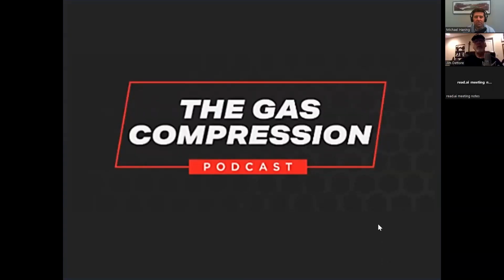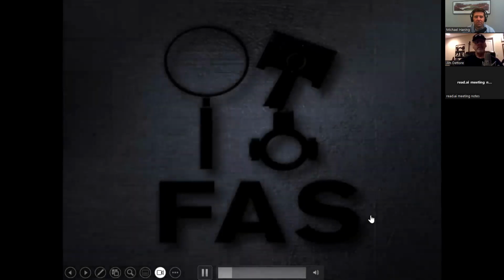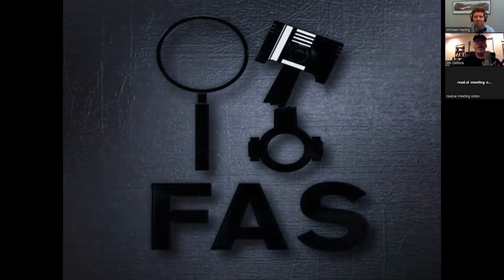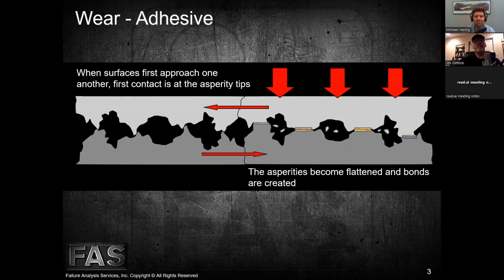All right. So as we start talking about adhesive wear, we'll roll through a few different slide pictures, which are basically just examples of what different types of adhesive wear might look like on various components. So when we talk about adhesive wear, and last week, Mike, we talked about two-body abrasive wear. Two-body abrasive wear was when these asperities or surface peaks come in contact with the opposite surface in a sliding operation, and it starts to cause very slight point contact tip wear. We referred to that as two-body abrasive wear.